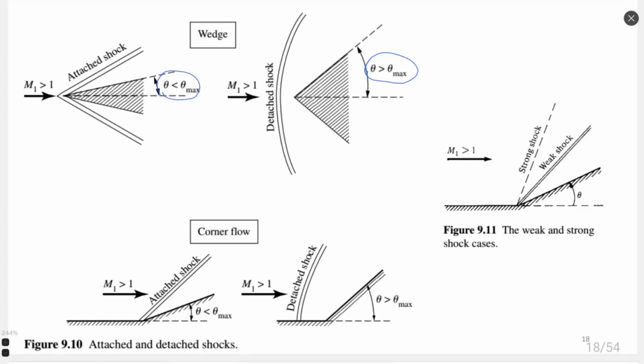But I think it mostly depends on how we interpret the geometry. It can be a different shape. We cannot say that it's a spherical shock wave, for example, or it's more, how to say, oval. It all depends on the geometry. There is no analytical model or calculation that tells us the shape of this bow shock wave or the attached shock wave. Shape cannot be found analytically. At least I never saw such a model.